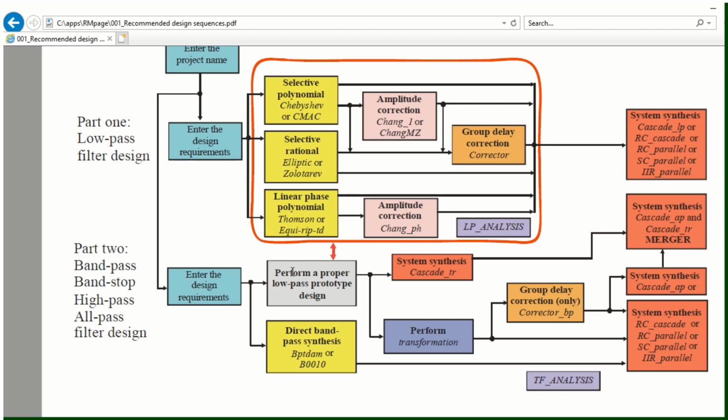To complete the schematic of the bandpass filter as a passive LC, we have to go backward to the low-pass prototype design and do whatever we did at the beginning. So create the transfer function of the low-pass prototype and then directly synthesize the bandpass selective circuit.